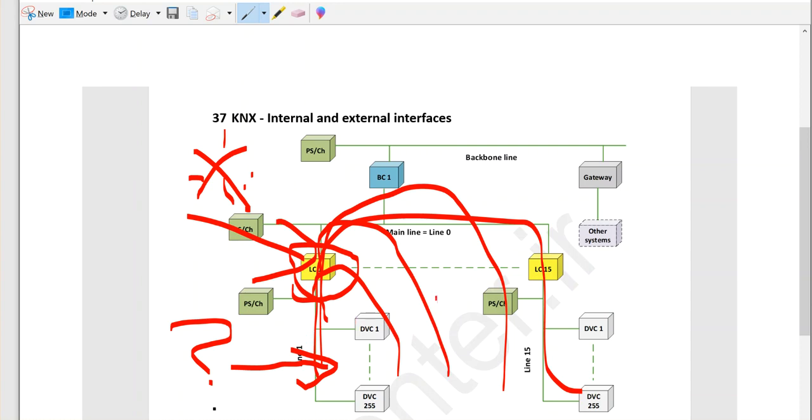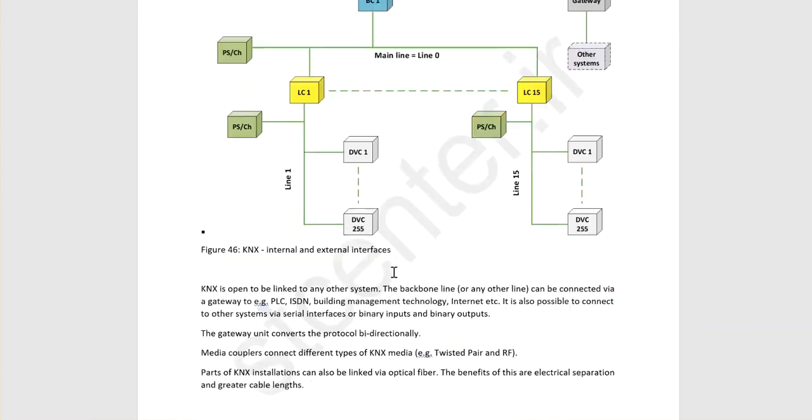But if, for example, you have a building with 500 or 1,000 Hitachi split units, and all of them have only one gateway to BACnet, and you want to use BACnet to KNX, you put the BACnet to KNX gateway on the backbone line or main line and communicate with all the devices through that one. Yeah, it's interesting. I hope it will help you.